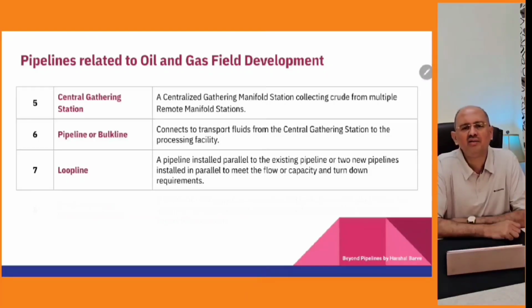Then there will be an increased number of wells, so the flow is going to increase, and then once again as the life goes further, as the number of years goes by, the flow rate might go down because some of the older wells might be depleting, and then they are producing less and less. So in the design lifetime of the pipeline, its capacity is like, initially it's going to flow less than its design capacity.